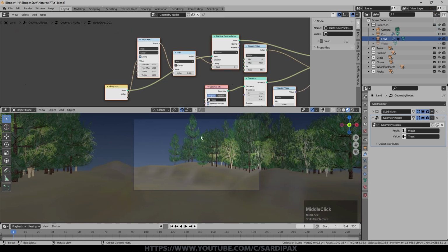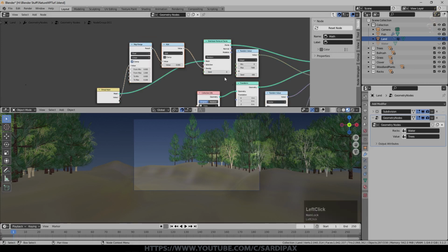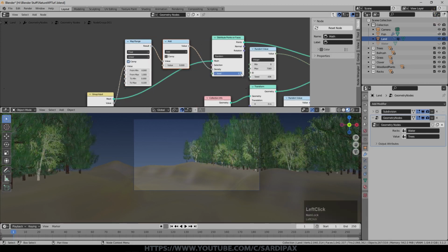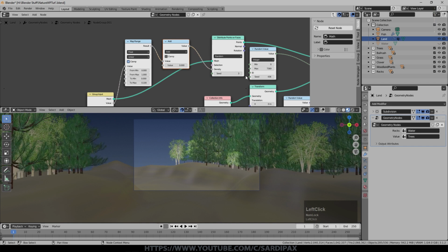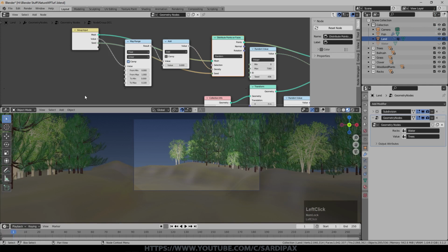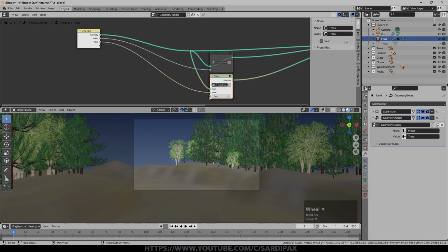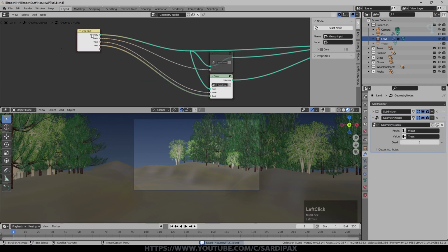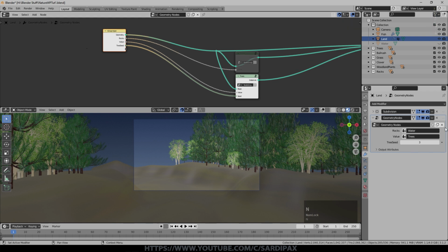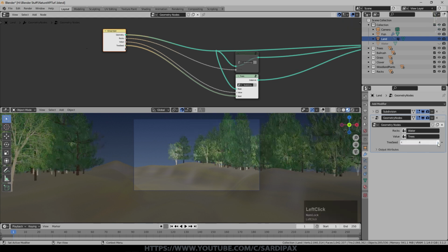And if we want to have different tree distributions, we will need to vary the seed. So I can click this here. Now, trees are obviously a significant part of the scene, so you may well want to be able to easily try different seeds for the tree. So again, I'm just going to pull that out to the edge of the group. It's called seed at the moment. And then I'll take that out to the edge here. We'll select the group input, go to group, and then we can select the seed and just say something like tree seed. So now we've got an input out here, which we can just play with to adjust what's going on there.